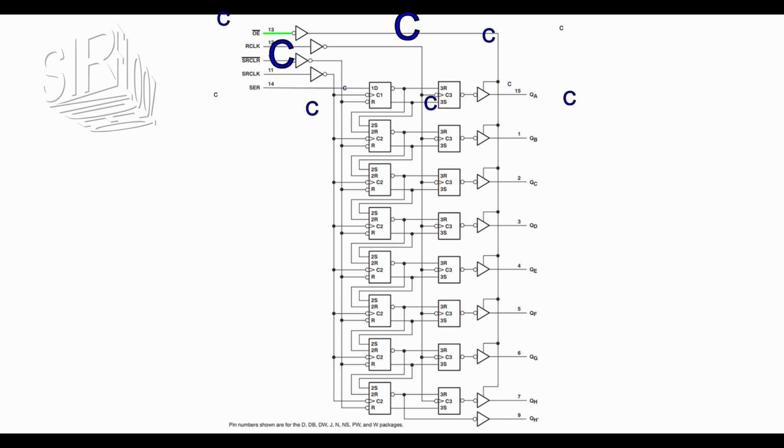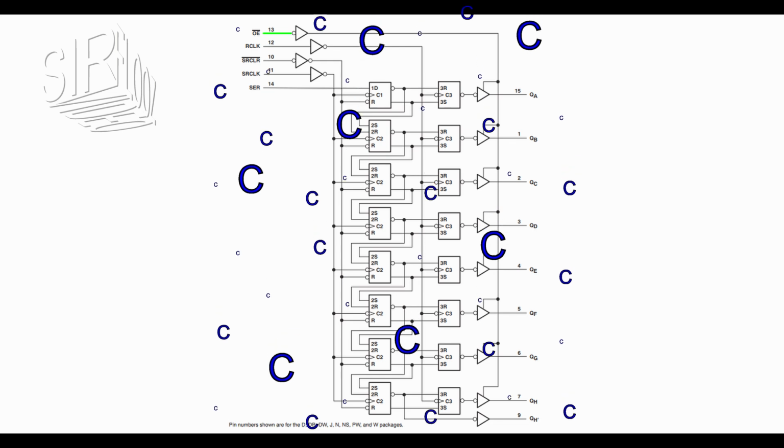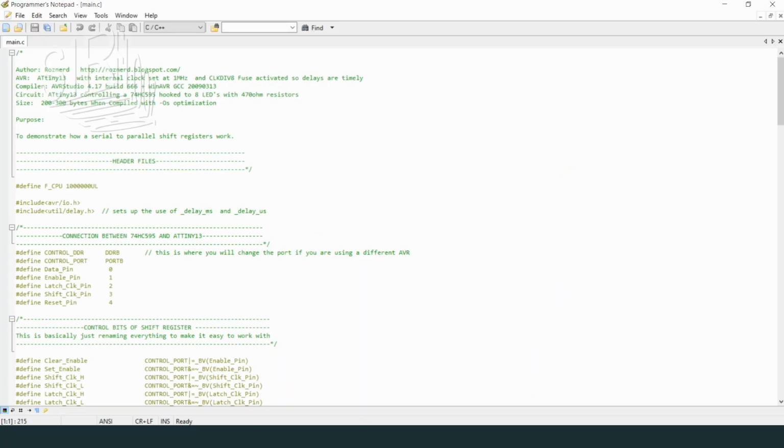To put the chip in action, I need a C program. After some searching, I found an example code on the web. That's the code I found on the internet. That's not the URL where I found it, but I think you can find it there. It's originally intended for the ATtiny13, but I will use it on the ATtiny85. These two chips are not too different. The ATtiny85 just has more memory and equipment on board, but the basic structure is the same.